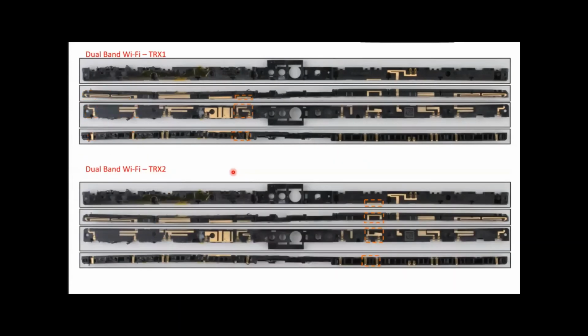And then if we quickly move on, we can see there's a Wi-Fi antenna here, which is another coupled structure. I have a fondness for coupled structures because they have very good wideband characteristics to meet the bandwidth requirements. So this is a meandered monopole, and then you can see there's a grounded structure coupled to it, and that combination works very well for coupling energy. And the thing next to it, if you're wondering, looks kind of weird and arbitrary. It's actually one of the devices that help with the isolation between this antenna and this antenna.